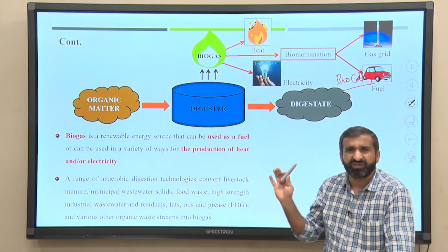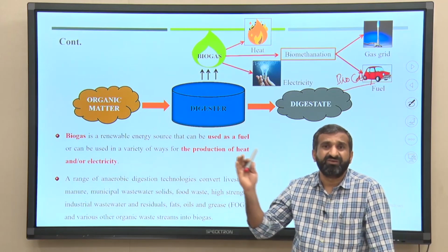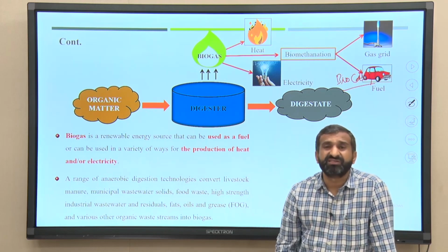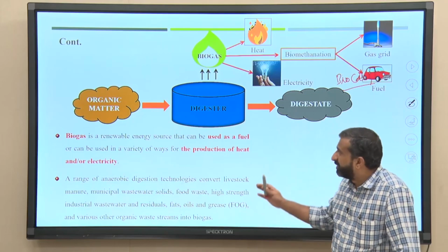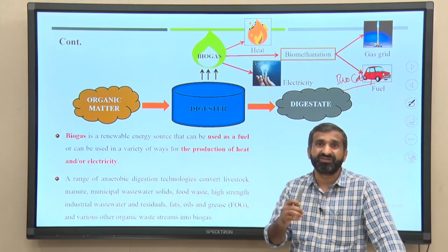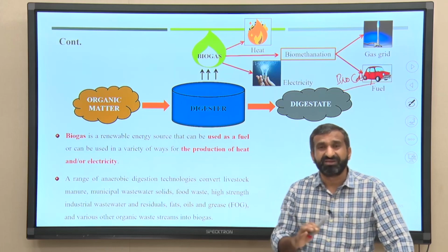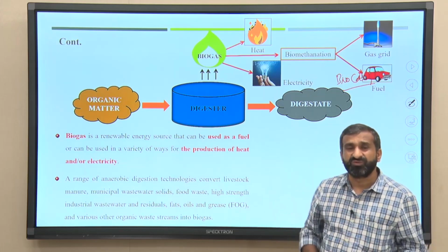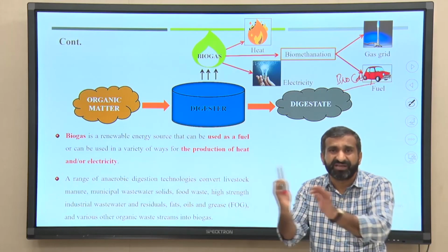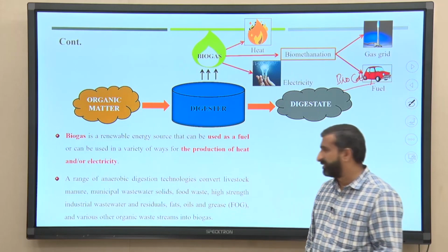There are a lot of successful anaerobic digestion processes, at various scales, available for sewage treatment and some other industrial wastewater treatment. Similarly, the anaerobic digestion process is also very popular for organic waste that is solid in nature. But again, we can't go directly for the solid; we have to make that material into a slurry, and then it is easy to go for the anaerobic digestion process.